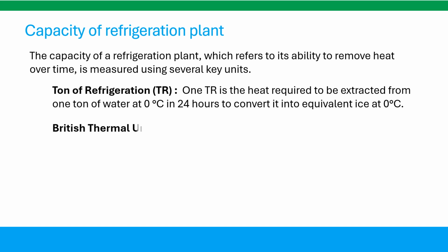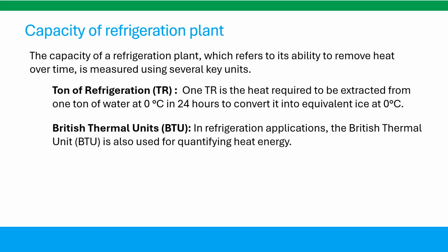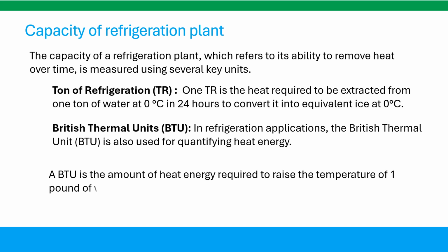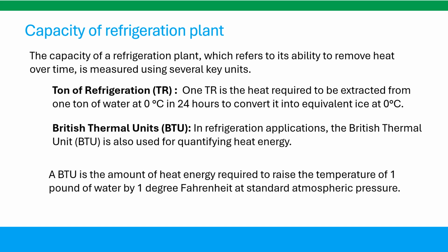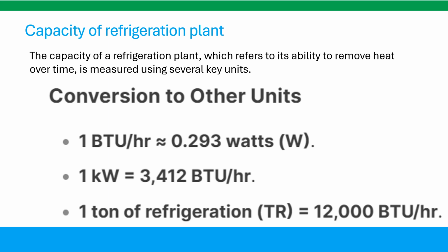British Thermal Units, BTU. In refrigeration applications, the British Thermal Unit, BTU, is also used for quantifying heat energy. A BTU is the amount of heat energy required to raise the temperature of 1 pound of water by 1 degree Fahrenheit at standard atmospheric pressure. Understanding the conversion between various unit systems is essential, as both systems are frequently employed in practice.